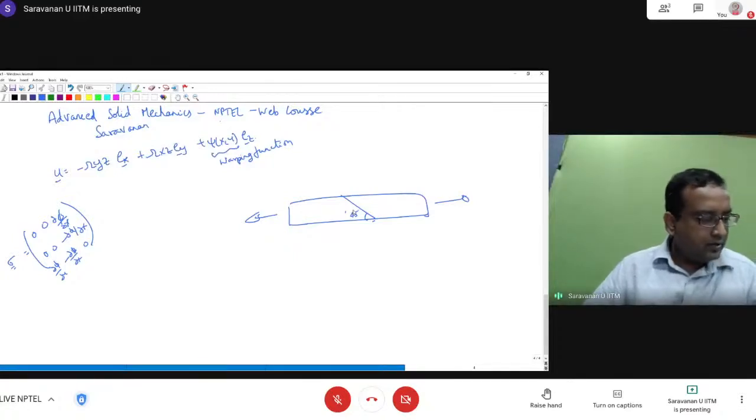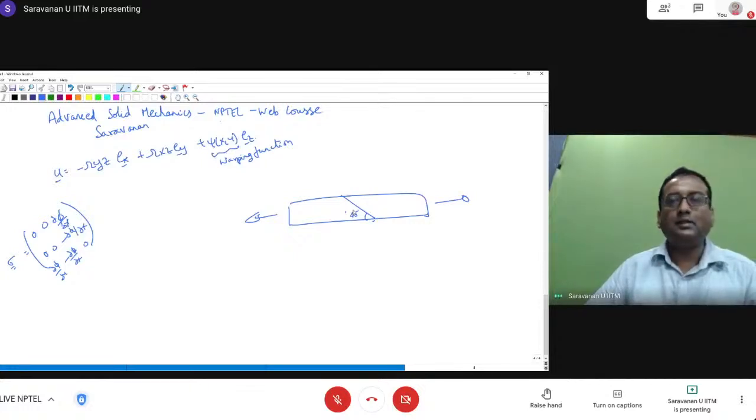Okay, how to capture the load displacement curve of a frame structure at post collapse? According to me, the post collapse behavior that you get experimentally depends upon the frame characteristics also. It's not something dependent on the frame alone, because it depends on the stiffness difference between the testing frame and the frame that you are testing.